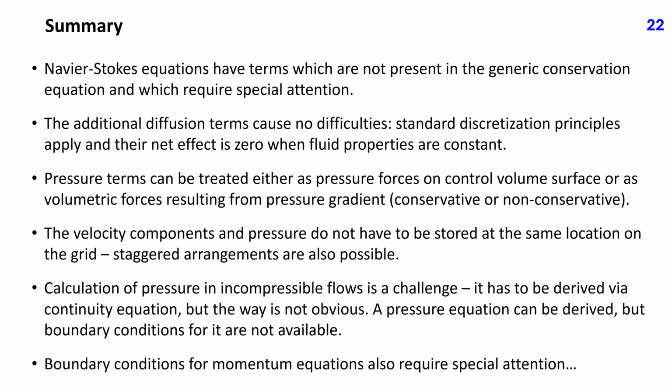Here is a brief summary of this lecture. Navier-Stokes equations have terms which are not present in the generic conservation equation and which require special attention. The additional diffusion terms cause no difficulties. Standard discretization principles apply, and their net effect is zero when fluid properties are constant.